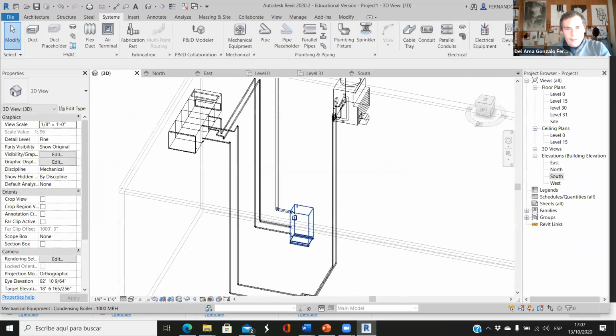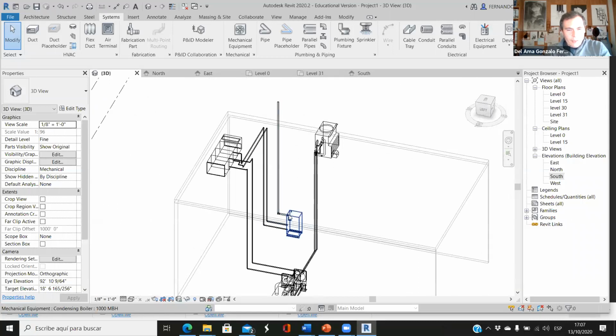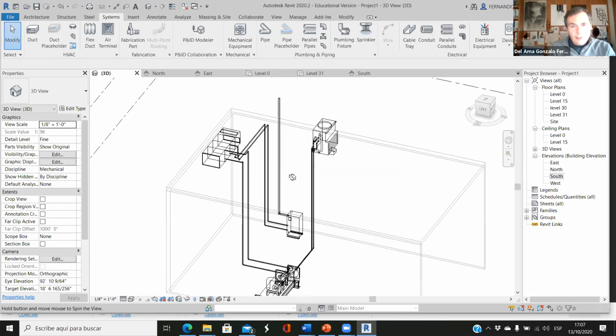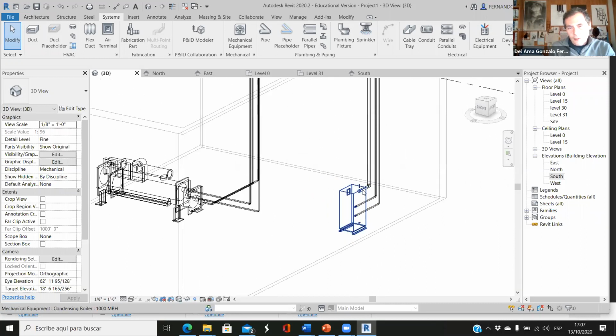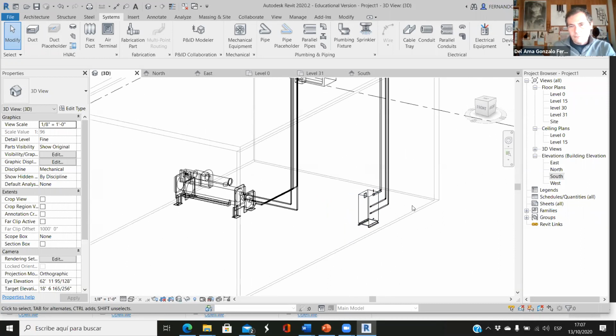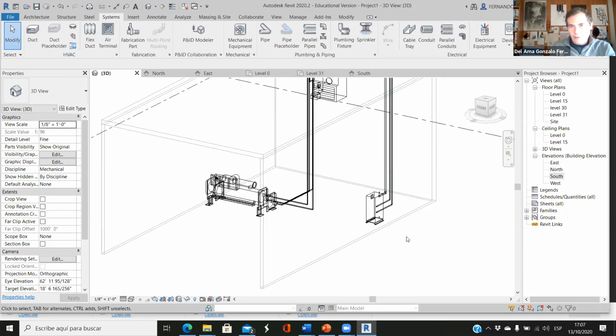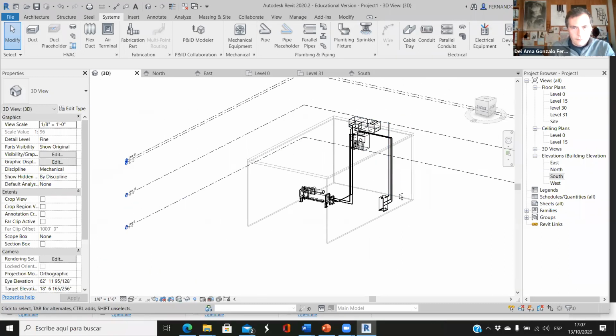And then we need something to. This is not a closed loop. This is just to get rid of the gases that we are generating here by burning gas. We are generating those gases in the boiler, and we have to get rid of them. And we get rid of them vertically. There is not an option to have a horizontal pipe and take it to the street. No, this is not an option. We have to go up.